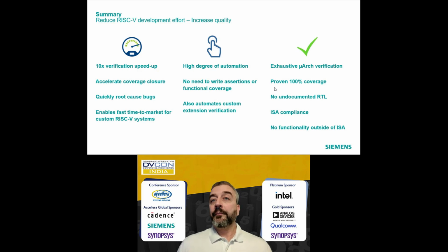And finally, this really gives you the full exhaustive formal verification. So it's not just the speed up side of things. You can get really the 100% coverage out of it if you additionally run this gap-free analysis that I was hinting at in the introduction. In this way, essentially, you make sure there is no undocumented RTL, because, as I said, the gap-free will make sure that your assertions form a real model of your design.